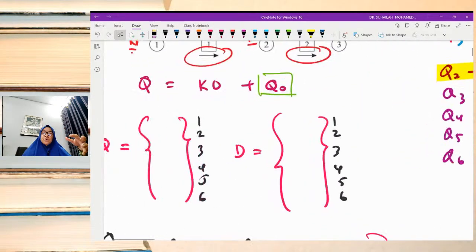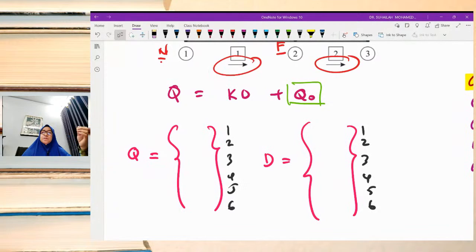So we should know that in order to solve for the unknown displacement and reaction, we will use the stiffness equation. In a beam, normally the member, the element, is subjected to loading, so we have to distribute the loading to the nodes, because a member or element cannot carry load.